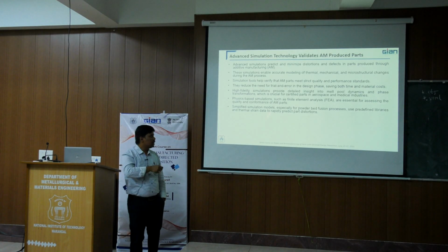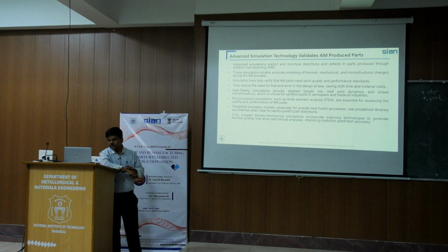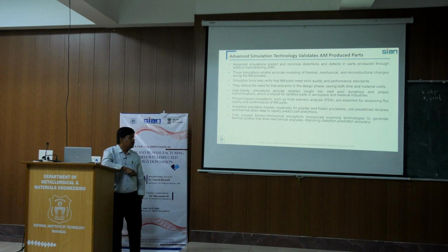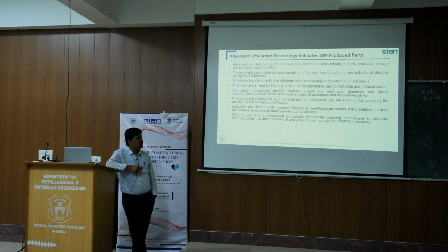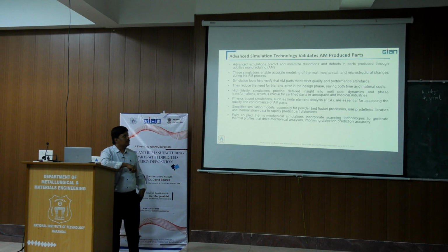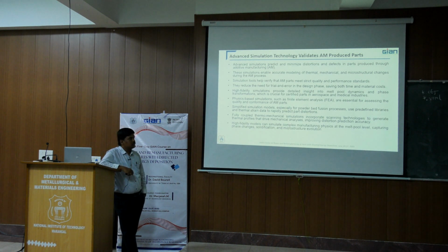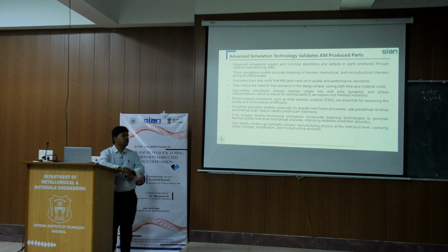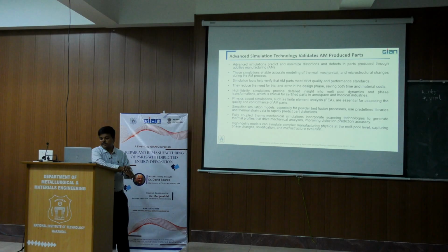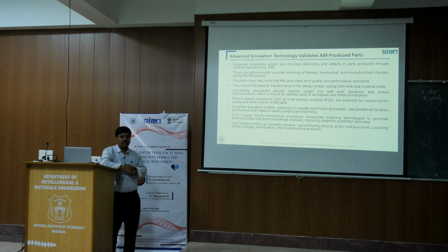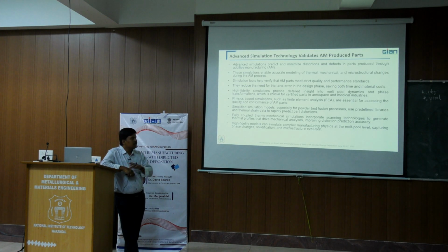That is where a lot of challenges are with respect to the laser DED process. There are also fully coupled thermomechanical simulations which can incorporate the scan techniques to generate the thermal profiles that drive the mechanical analysis, to improve distortion, friction and accuracy. Even the high fidelity model can simulate the complex manufacturing physics of the melt pool, capturing the phases and the solidification as well as the microstructural evolution. Nowadays we have very advanced numerical models that help us understand the microstructure developed in the manufactured components.